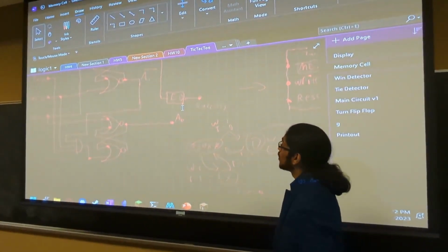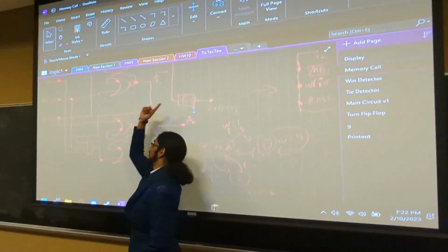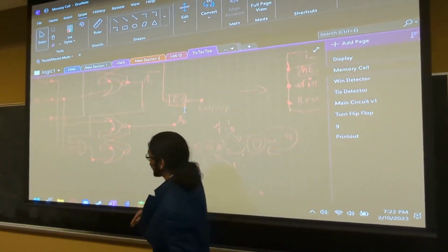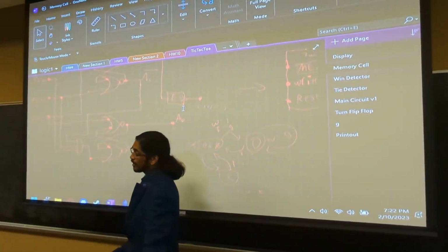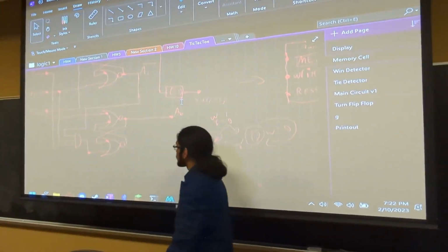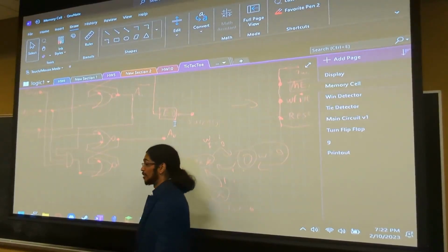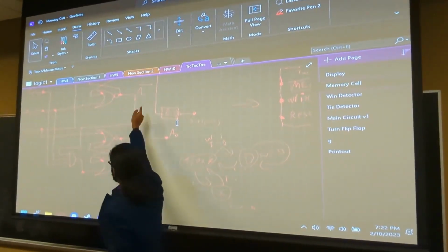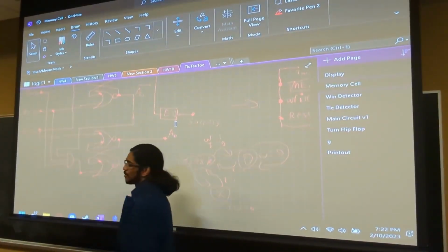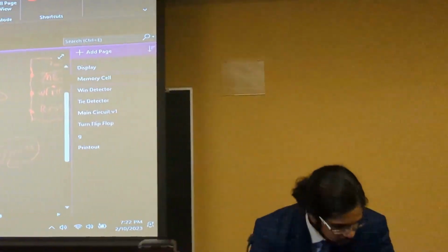Okay? And so no matter what, if the write signal is turned on, then we just need to write a 1 to the occupied bit, right, no matter what. But the bottom guy who's handling X or O should only write a 1 if it's X's turn, right? Otherwise, it should just write a 0, or stay as 0, because it's 0 by default. And then when this guy is turned on, it doesn't let the bottom guy be written to anymore until we hit the reset. Okay. So let's build that.